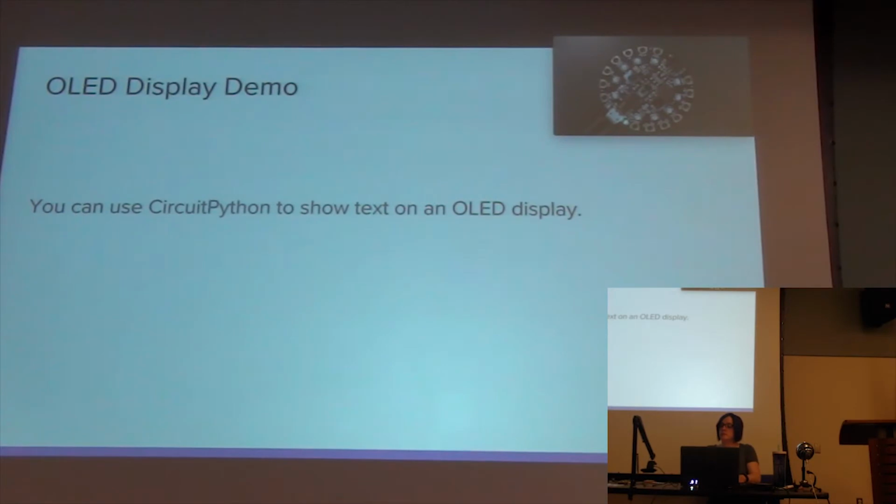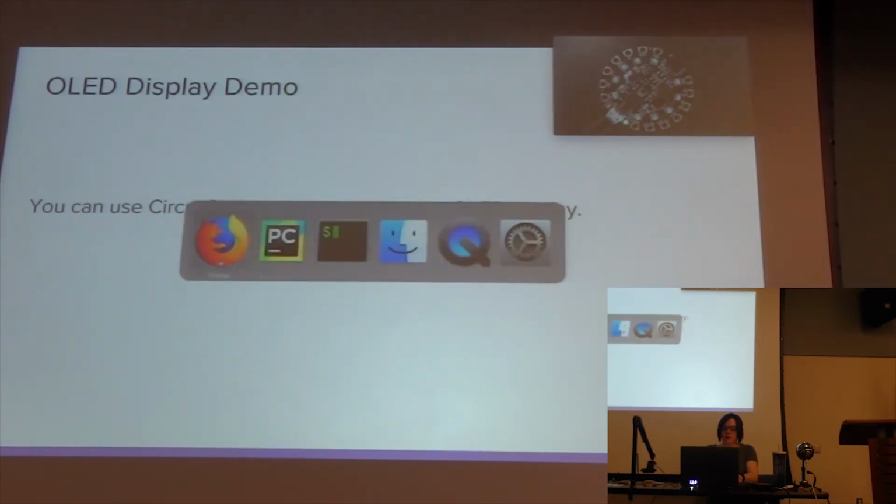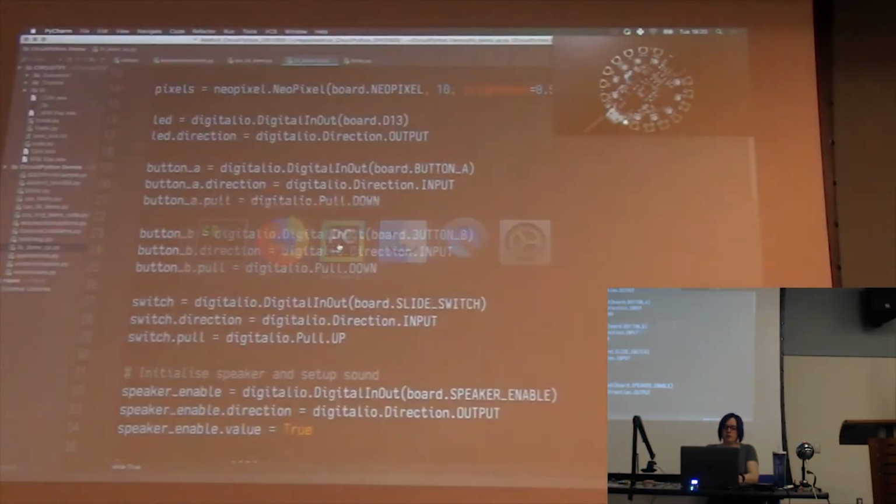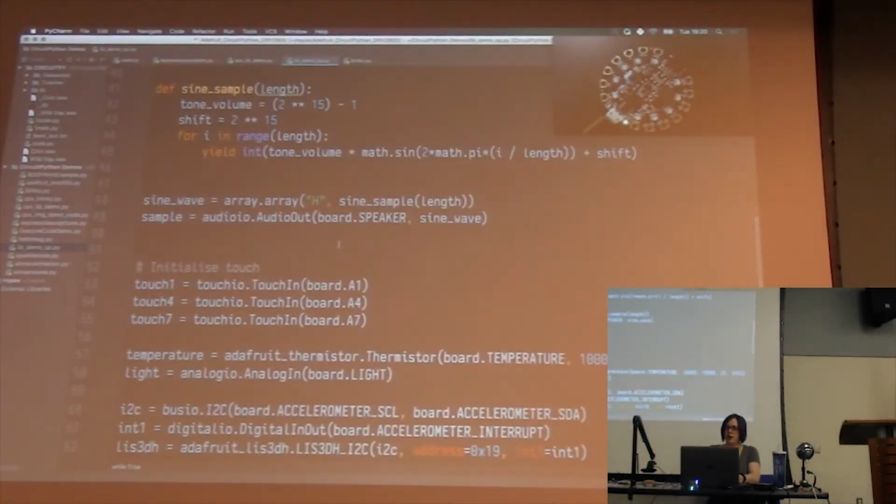So, all right. Those tabs around the outside of the board, those are actually GPIO tabs, and to use them as a touch sensor, you're just putting it in some kind of a high impedance state. It actually grabs the change in capacitance, and that's why there's a setting for threshold. It calibrates when you restart it, but for example, if you have it attached to, say, fruit, because you're doing a little fruit project, it can sometimes have problems calibrating. So you can set a threshold that changes the amount of capacitance that has to change before it considers it a touch event. You cannot use it as a GPIO output and as a touch output.